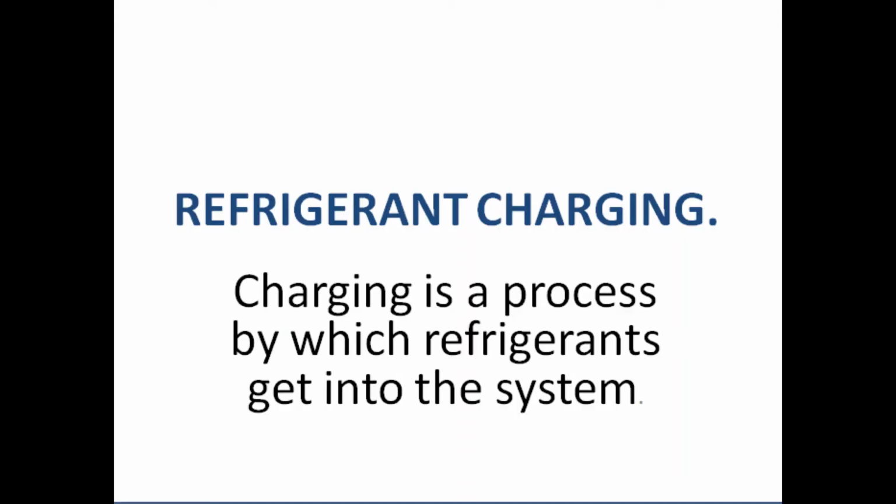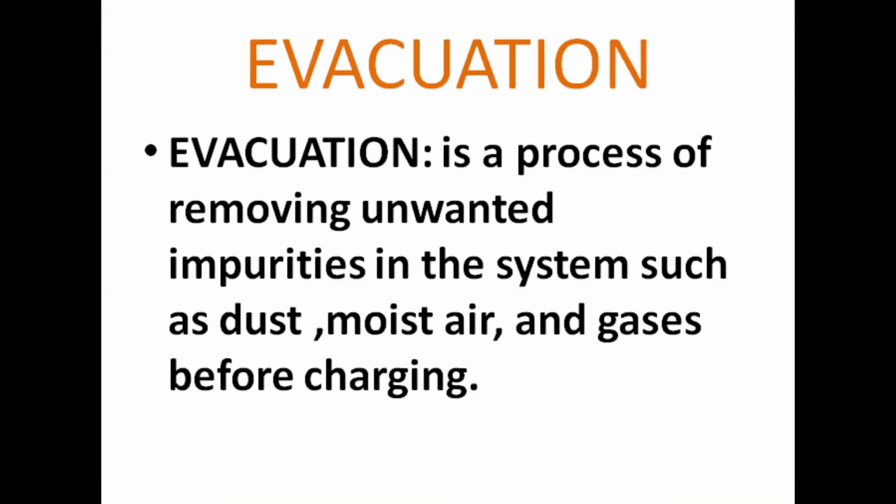Yes, we know that refrigerant has to be introduced in the system, and such a process is called charging. Charging is the process by which refrigerant gets into the system. But before starting this process, there is one important process we have to begin with, which is evacuation.